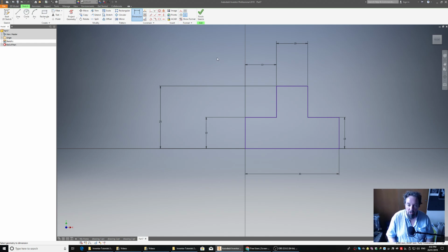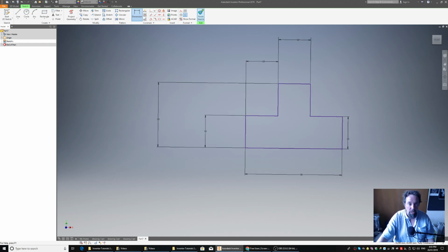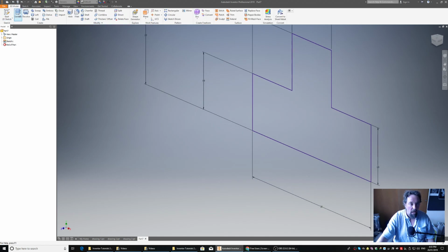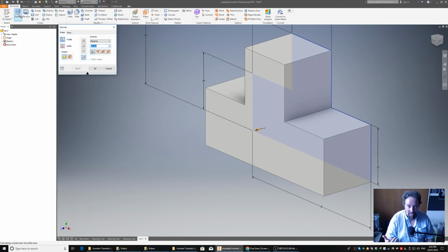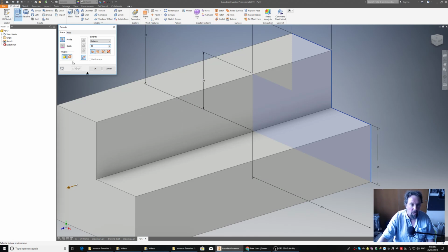Where this technique's really handy is where you've got difficult sketches or problem shapes and you can't easily remove them, but you can draw the shape basically right and then use the sizing to get it right. So once you've got the shape right, and you'll notice all these have gone blue, so they're all constrained. That's a new word, constrained, which means held to, they won't move. Finish sketch, extrude, it automatically selects the shape, we know we want to go 50 millimeters long, and go OK.